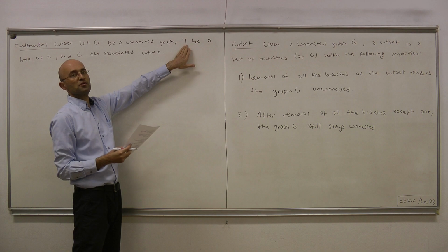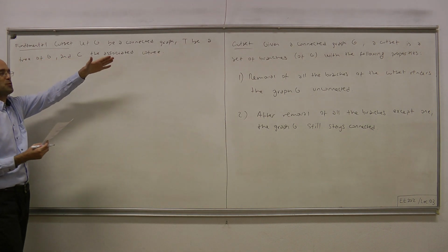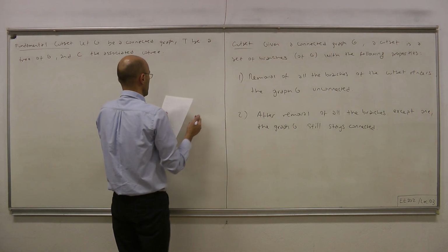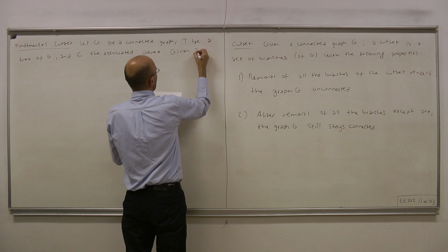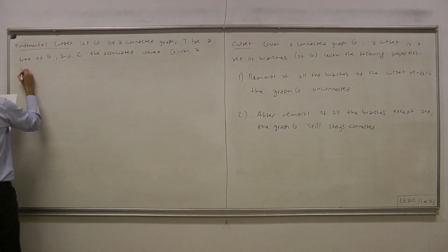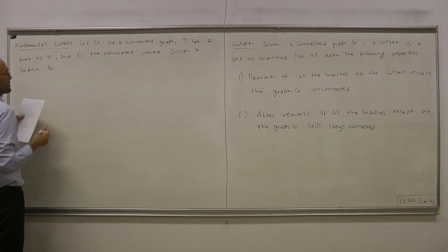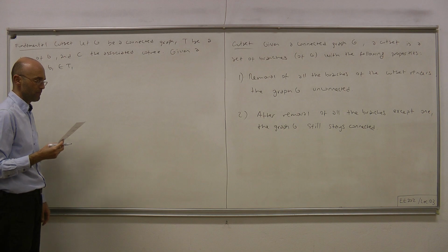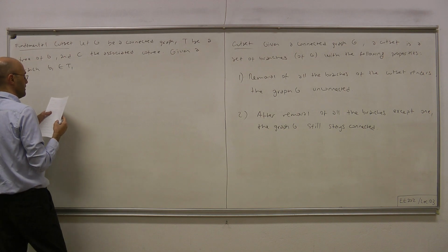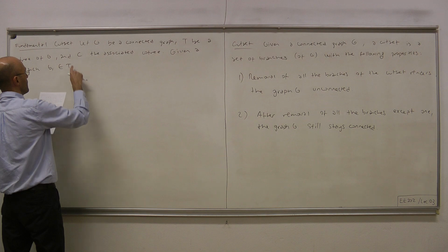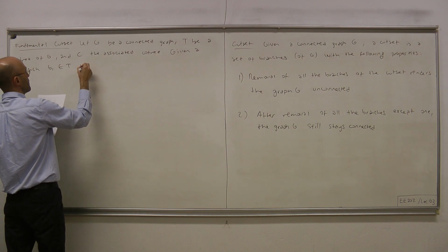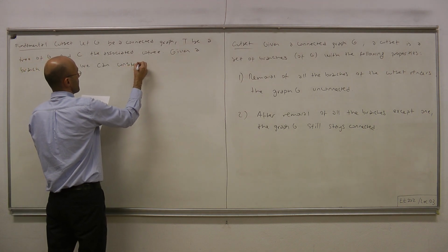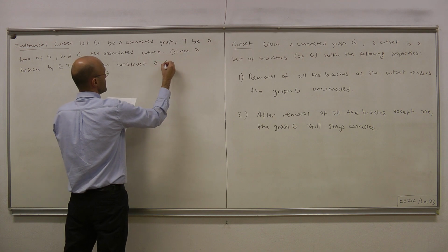For that, we choose a tree, or perhaps we're given a tree, and then once we have the tree, we automatically also have the Cotree. Given a branch, let's call it B1, that belongs to our tree T, we can construct a cutset, it turns out.